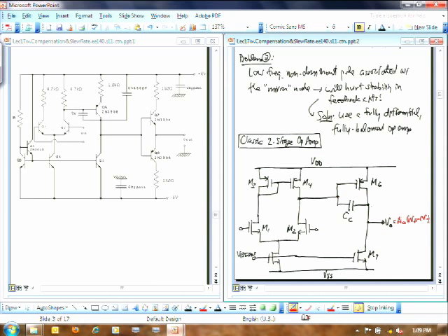Okay, and you can do the exact same thing on this side. If I go from here to here, that's negative. But then there's another negative there which makes it positive. So this is the positive terminal. So that's a skill you ought to have. When you see a big op amp circuit like this, you should be able to say which is the positive and which is the negative terminal. Now obviously the other skill you should have is to be able to calculate the gain of this thing, and at least write the equations for the gain.